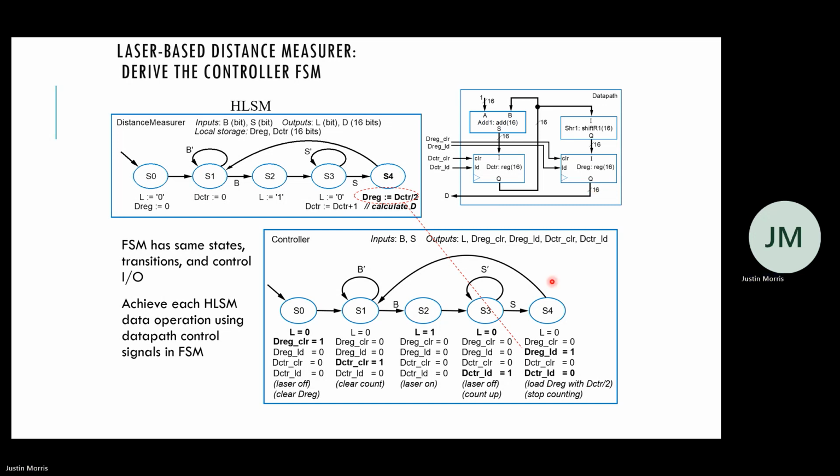And now once we have that, we go to S1. And it displays the distance in meters, right? So now that we have, this is a finite state machine, right? It has multiple outputs, but it just has 5 states. We could create the K-maps. Well, create the excitation table, then create the K-maps, get the Boolean logic equations, draw the circuit.